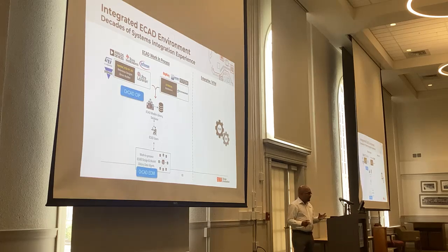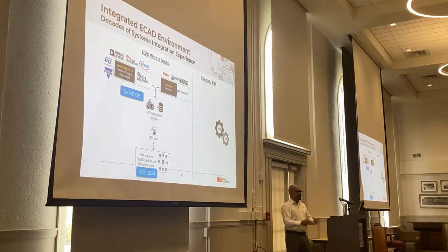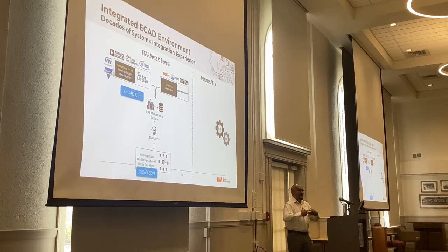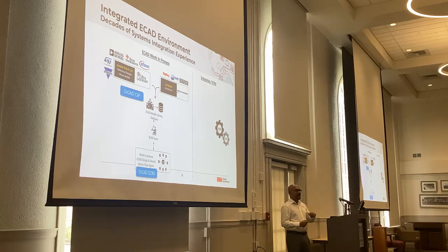And now you need new components, right? Because you have a library of symbols, footprints, 3D models. What do you do when you need to add a new component? You want to make sure that any new library part that you add is a good part, is active. You don't want to add obsolete parts into your centralized library because then all the designs start using that part and then you have to clean up.